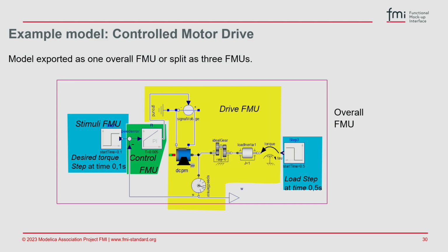I also have a question. Once we export the FMU from a certain software, is it also possible to change it? We'll show that in part 2. You can, for example, change parameters, or some connections within the model. If these would be switches that you expose, for example, in the form of parameters, you could do that. But typically, the structure is fixed.